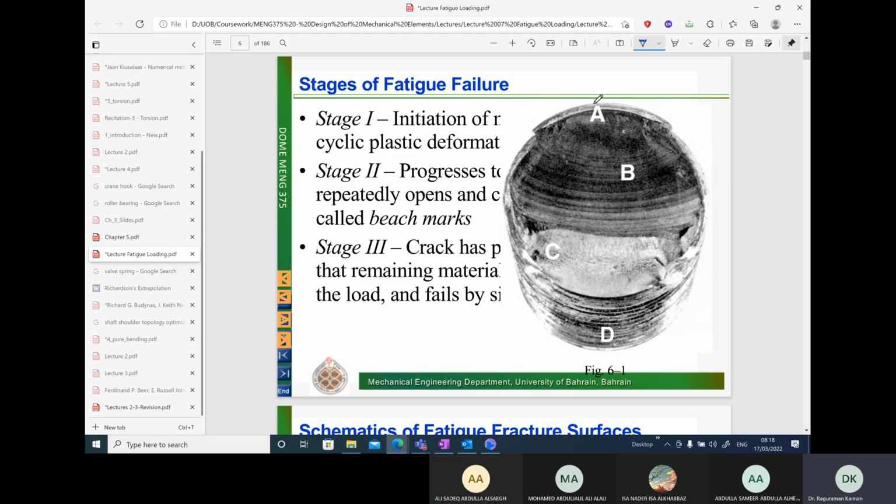And right on the surface of the bolt where you have threads, you have change in geometries. For example, if you look at the thread, these are V threads. These areas act as places where there can be enough stress concentration, and because of these stress concentrations on the V threads, what you will have is crack initiation. Very high stresses right on the surface, you can have crack initiation.